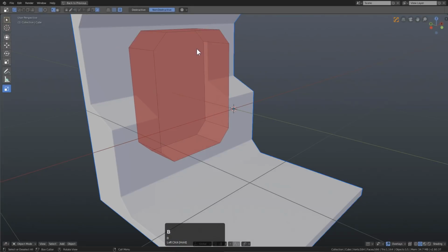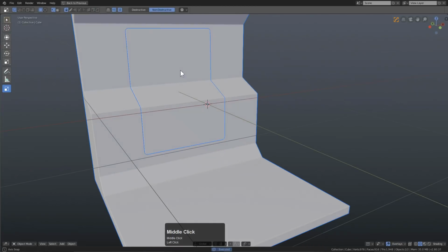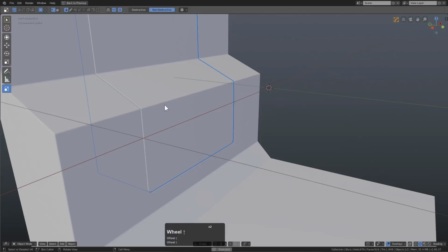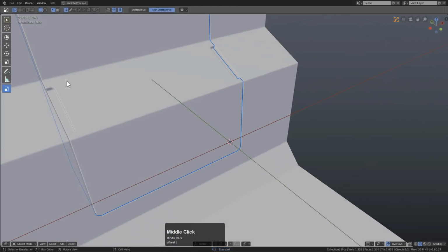And this is something that I think will be part of Blender in the long run and won't be changing. And when I first discovered this, I was like, oh my god, we have to put out a video immediately. I have to do a PSA to let people know that you can actually mirror in Boxcutter non-destructively and continue all your cuts without any regard of what happens in between.